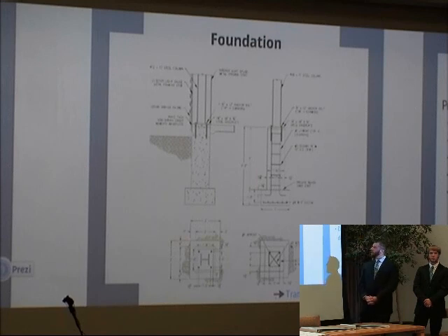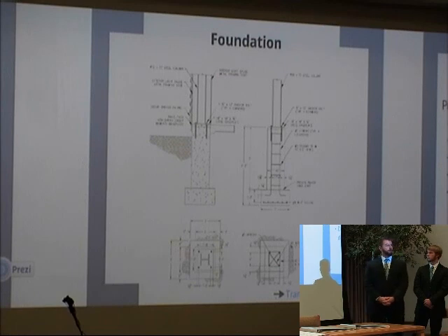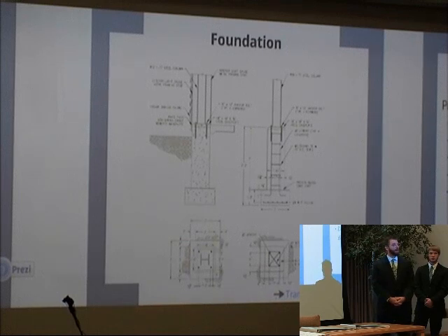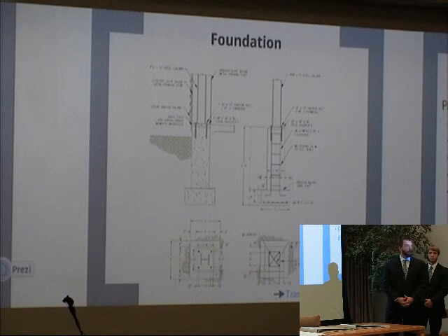So moving up to the column, at the interface between the footing and the column itself, we provided a raked construction joint for phased pours of the concrete. As some of you probably know, you have to wait 7 days after pouring the first phase of a pour to pour the second before it bears any load. So the footing would be poured, and then 7 days later the column, and we have to provide a raked construction joint in order to achieve shear.